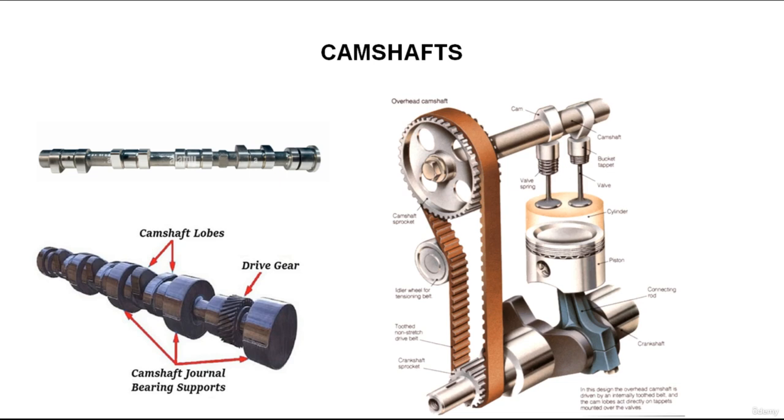the combustion cycle takes place in four strokes of the piston: the intake stroke, the compression stroke, the power stroke, and the exhaust stroke. The camshaft is driven by the crankshaft through gears or sprockets and a cogged belt or timing chain. The camshaft turns at half of the crankshaft speed and rotates one complete turn during each complete four-stroke cycle.